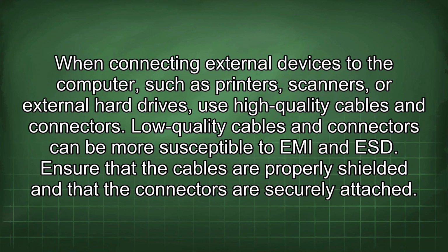When connecting external devices to the computer, such as printers, scanners, or external hard drives, use high-quality cables and connectors. Low-quality cables and connectors can be more susceptible to EMI and ESD. Ensure that the cables are properly shielded and that the connectors are securely attached.